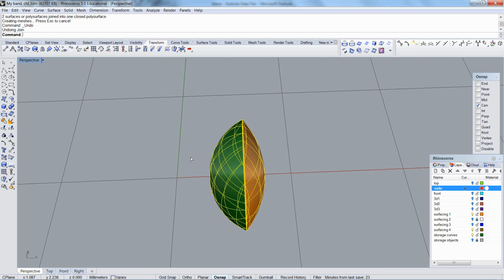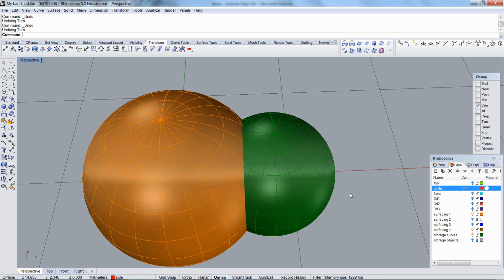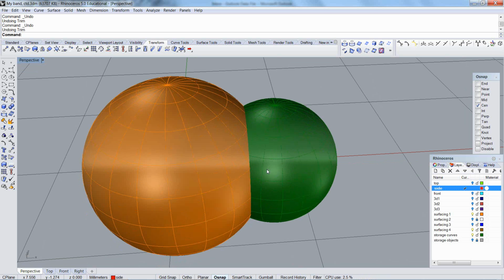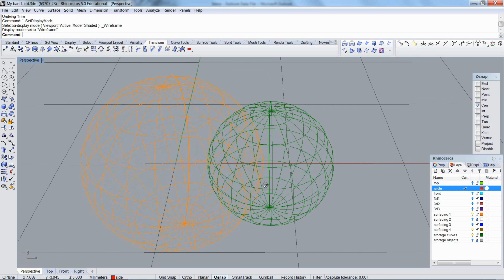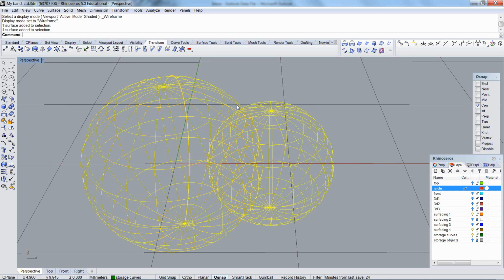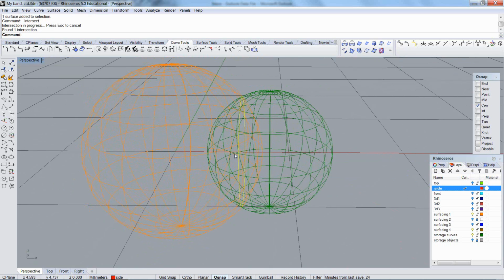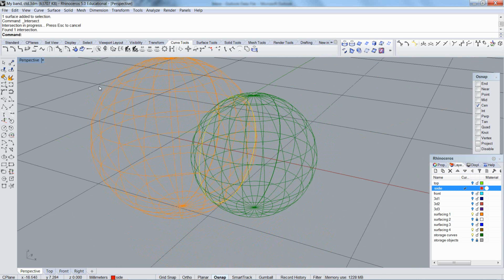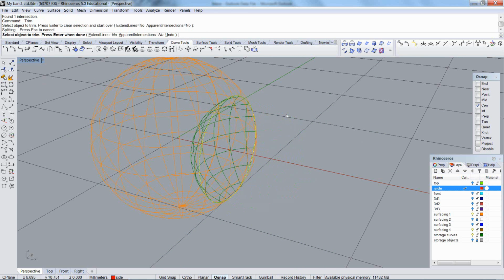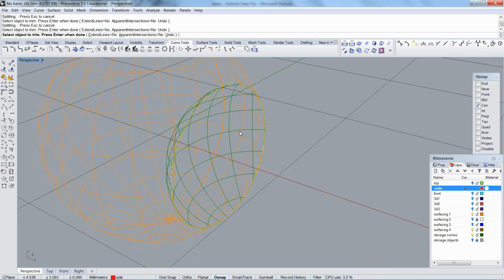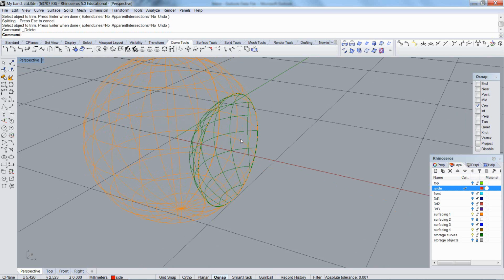So it is, you can do it by hand. It's hand stitching. If your forms are complicated and they don't want to trim off each other, which is usually the case, you can create an intersection curve. Select your two objects, click Object Intersection on your Curves from Objects pop out. That'll create a curve object, curve geometry. Then you can use the curve to do the same. Throw away the curve, join them together,